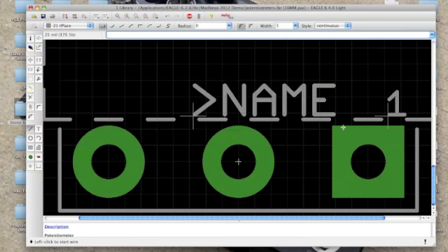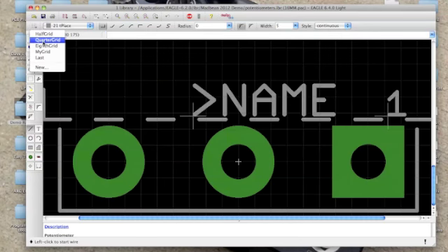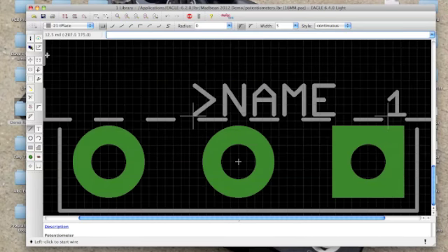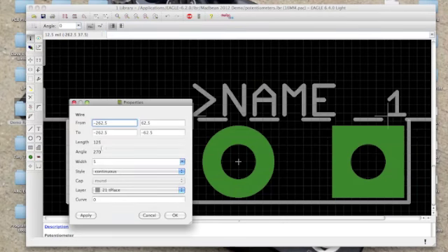So now it's also farther away from the pads because of the grid size that I have. My lines snap to the grids that I have. I could, for example, go to a smaller grid size, go half grid, which is 12.5 mils. And I can move this line closer on the bottom, but keep the sidelines farther, or put them closer. Why don't I put them closer? I'm going to extend this line up a bit. I can have a lot of control over these lines as well.